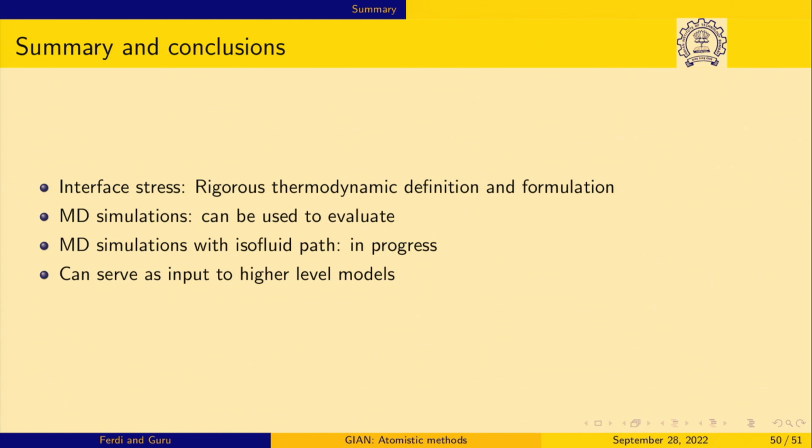You can evaluate interface properties, except that you cannot do molecular dynamics simulations. If you want to see the interfaces, you have to do Monte Carlo simulations, and of course, this has been done again by Mishin. So, he took some MEAM potentials and some nickel aluminides, and he created solid interfaces, did some semi-grand canonical Monte Carlo simulations on that, and using a similar formulation you can derive the interface properties.